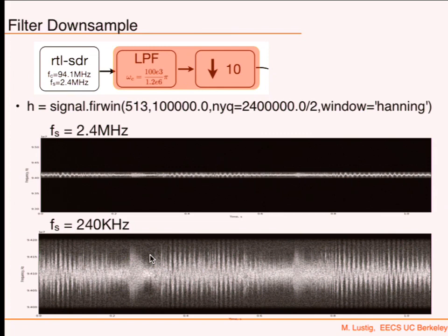Now you're going to recapture a signal again for 10 seconds. And you're going to go through this processing without displaying this. After the filtering and decimation, then you'll display 10 seconds of that. That's okay. That's 10 seconds at 240 kilohertz. You know, computation is not too bad. 10 seconds at 2.4 megahertz is pretty intense. Okay, so you display the spectrogram pretty quickly.